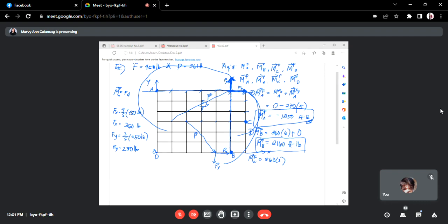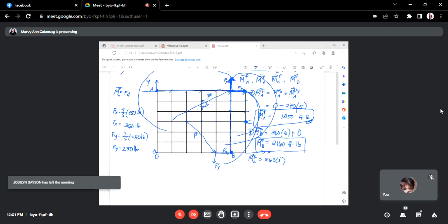It turns clockwise. You might say to go from there through Fy, but that is not possible, because that would rotate it twice. You have to consider which side it is on. So the rotation of Fy about C is clockwise, therefore positive. And our moment arm, the perpendicular distance of Fy to C, is 1. So plus 270 times 1.